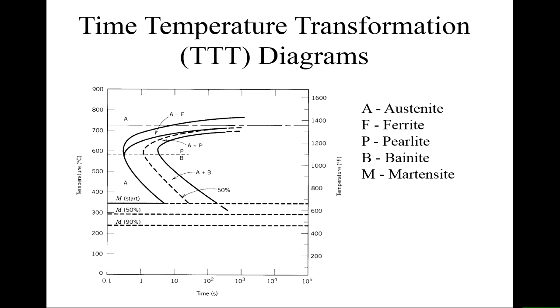Now, unlike in a conventional heat treatment furnace where you put the whole component into the furnace, with a welding process you're only heating the area around the weld. So there's a lot of metal generally around the welding region that can conduct the heat away. So the cooling rates that we tend to achieve in welding are much, much higher than you would normally achieve in thermal processing in industry.